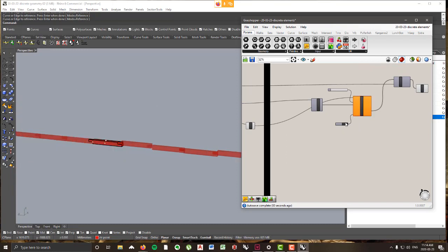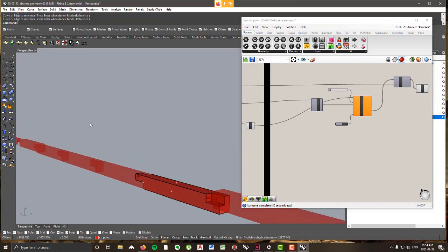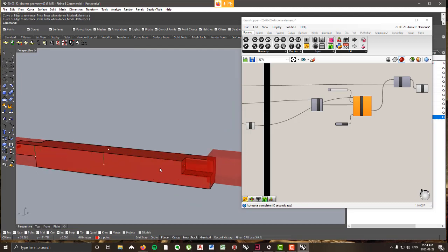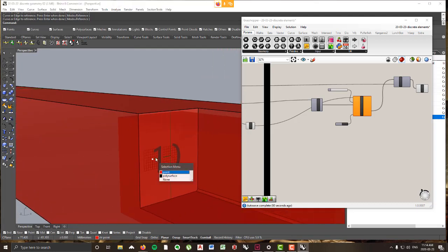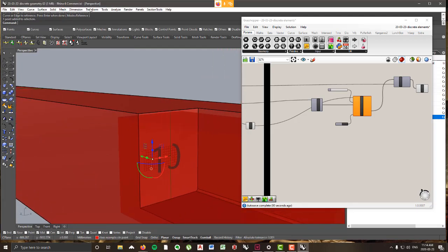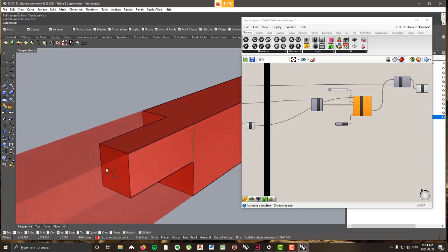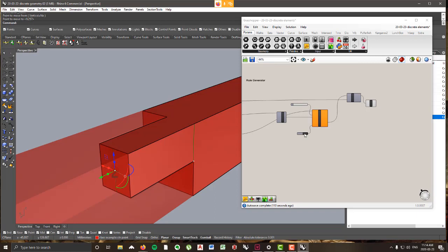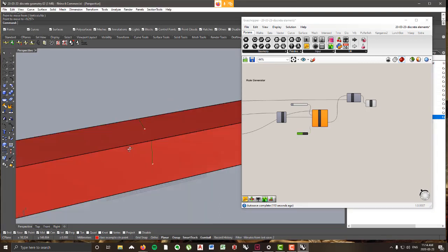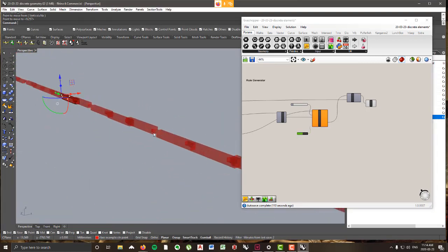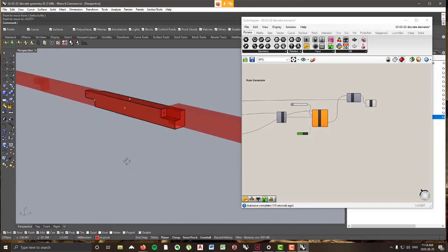updating. So you can see now all the connections I'm getting by default are kind of these rotating pieces here. What I want to do is take this center point that I'd shifted over for selection, move it back to the actual center. Make sure your point snap is on. So that shifts there. Find the other point we've shifted over. This shifts there. We can reset our array. So now you can see we're just creating this long linear array like so.